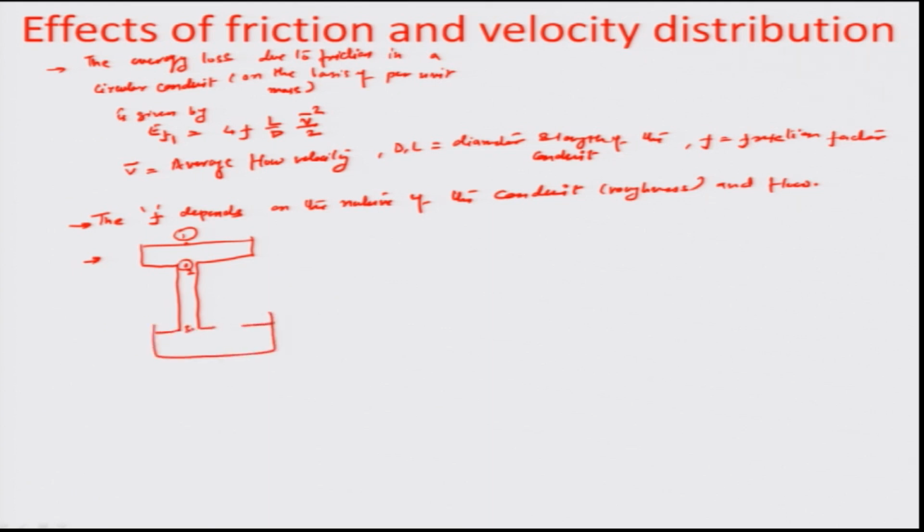So, that is how we had figured out this vertical gating. Similarly, for the horizontal gating system, if you may recall, we had a pouring basin opening up into a sprue again, which was slightly tapered to avoid the aspiration effects, and there of course was a runner which was designed to enter into the mold as if the mold gets filled up from bottom up. So, that is why it is called a bottom gating system.